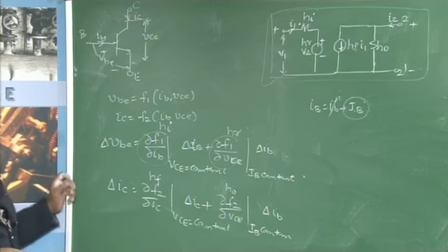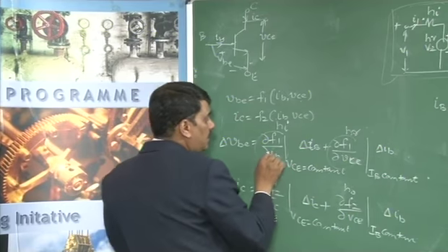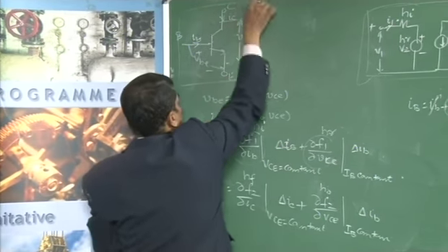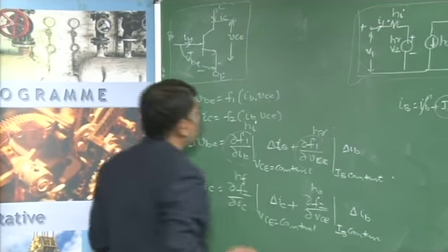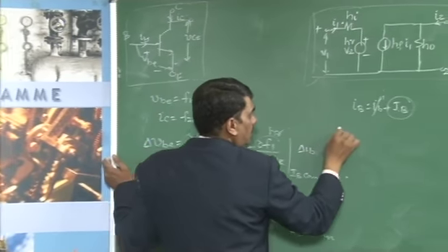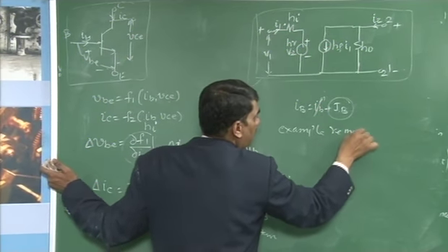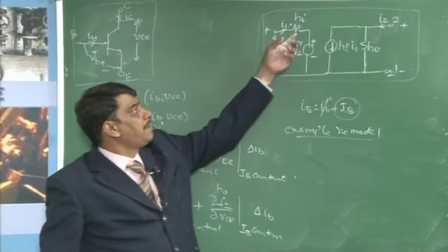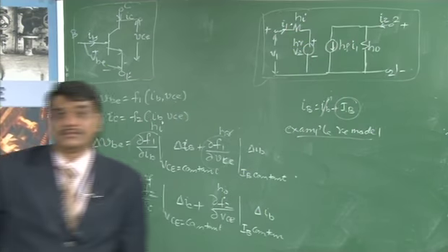In the next class, we are going to determine the relationship between these using this relation, and then define an equivalent circuit for this transistor. Today we are summarizing this class or session with examples on the RE model, and then defining the transistor hybrid parameters Hi, HR, HF and H0. Thank you.